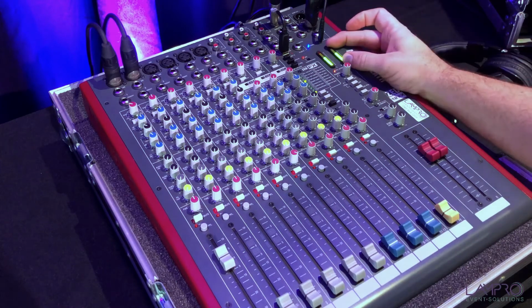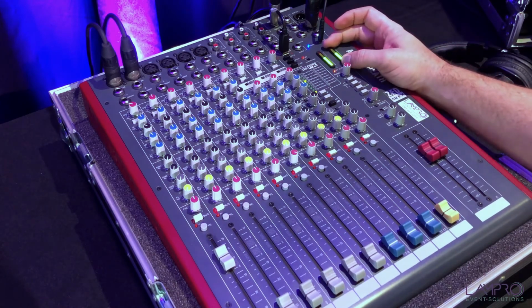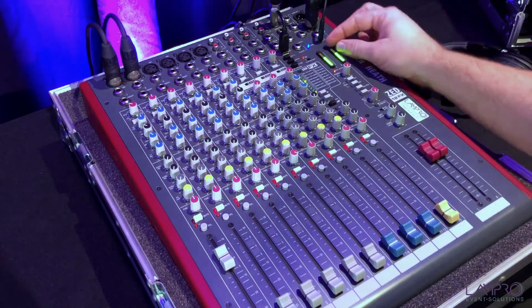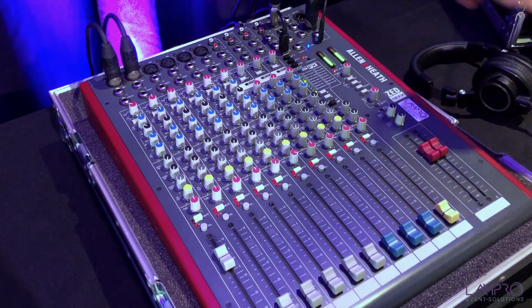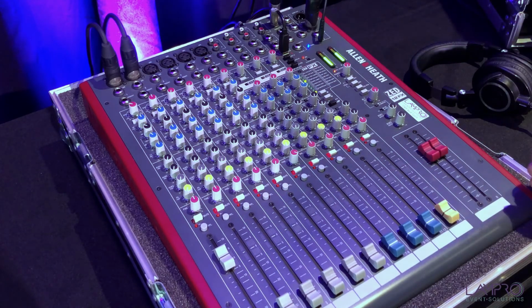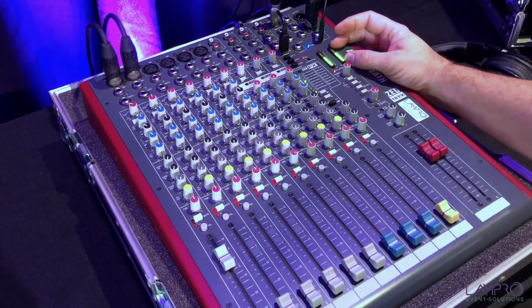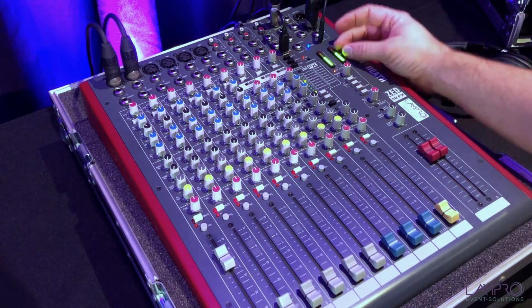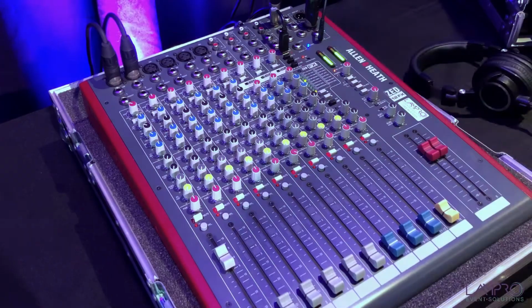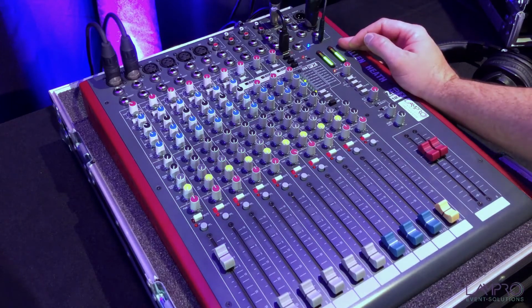This is always a good level to set for any incoming audio signals into any of your channels, whether it's the mic or line inputs, to leave yourself sufficient headroom for any fluctuations that might take place with the incoming audio signals. This commonly happens with vocal mics or instruments where there might be fluctuations in the audio levels. So always try to set it as close to 0 dBs as possible to leave yourself some headroom in case the audio levels increase.